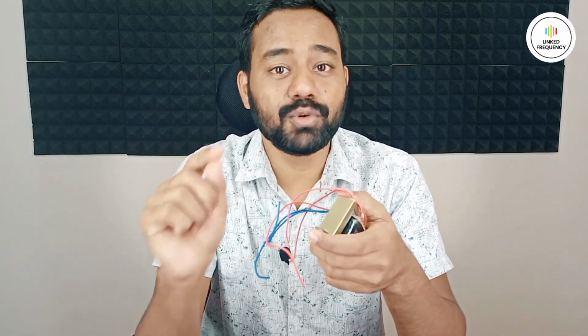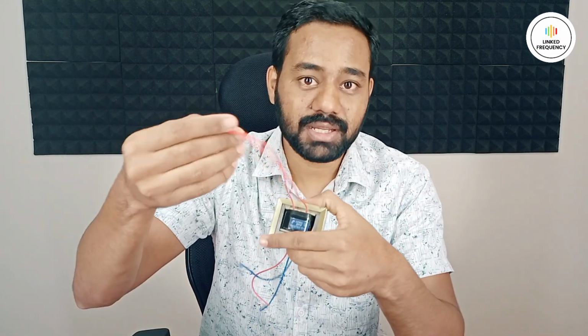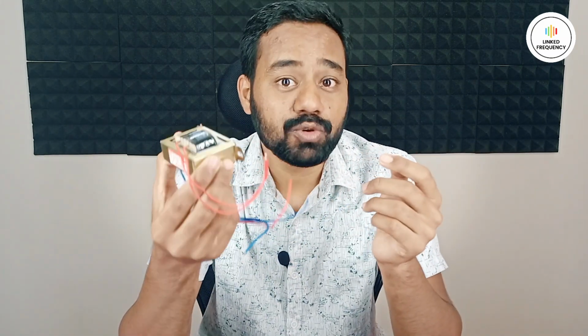In case you don't want to place this transformer on the PCB, you can create a connector where you can connect the output of this transformer and the input to the direct AC supply using wires, and mount this transformer on the panel or the box of that entire project, which is possible. In that case, you need to use only the schematic symbol, not a PCB footprint. If you want to use it, you can still place it and ignore it while soldering the component. But still, those permutation combinations are available for you.